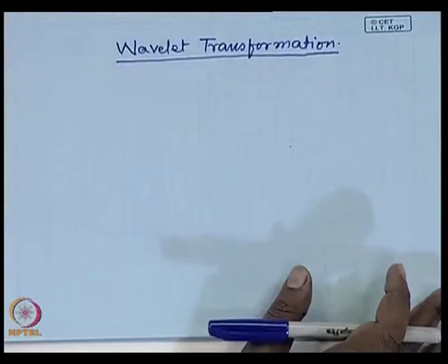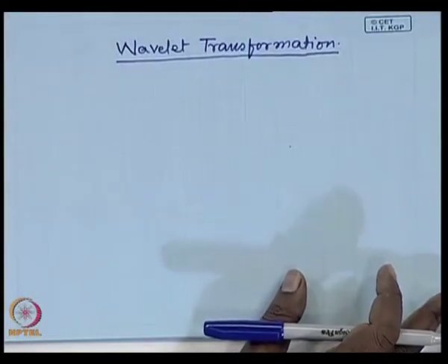When you take the Fourier transformation or cosine transformation, what is it that you do effectively? What does this coefficients mean, whether it is Fourier coefficients or DCT coefficients? Whatever is the set of data you have, you represent that set of data by a set of sinusoidal waves.